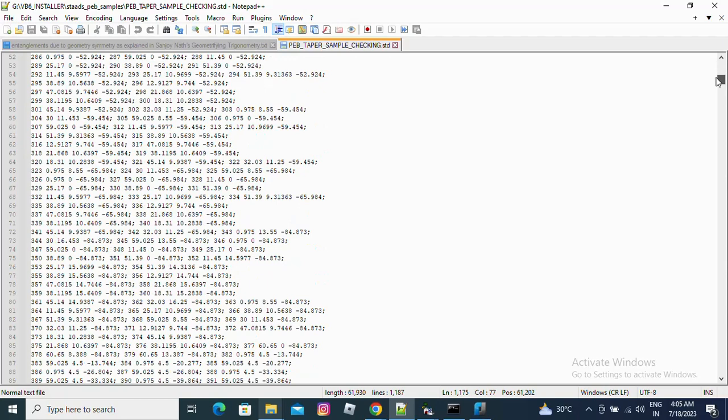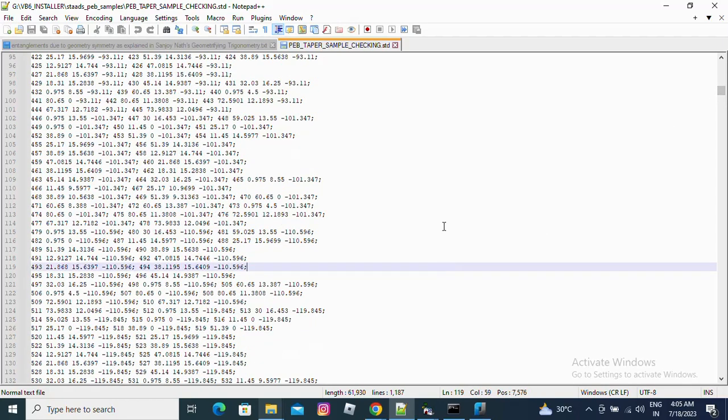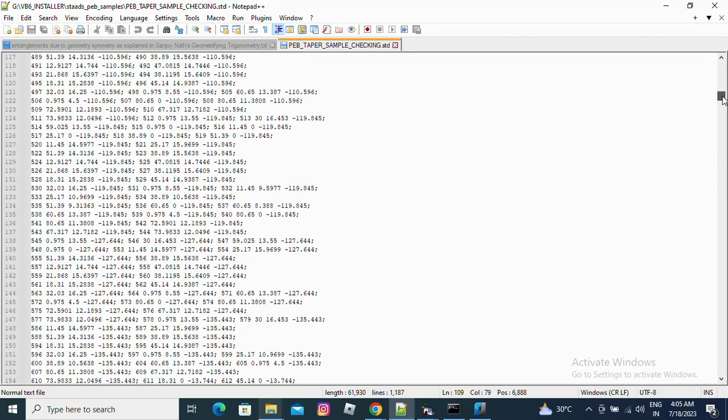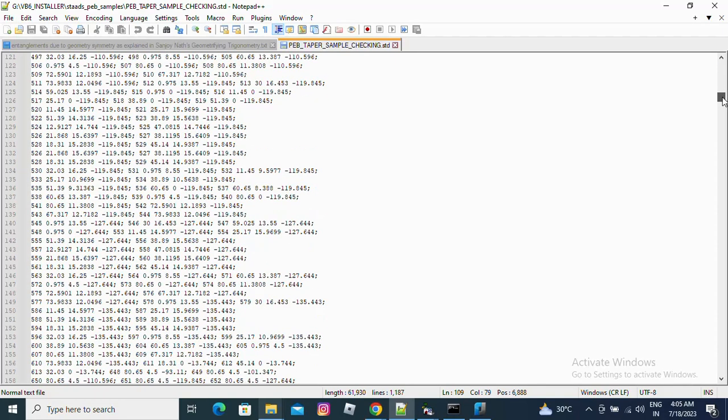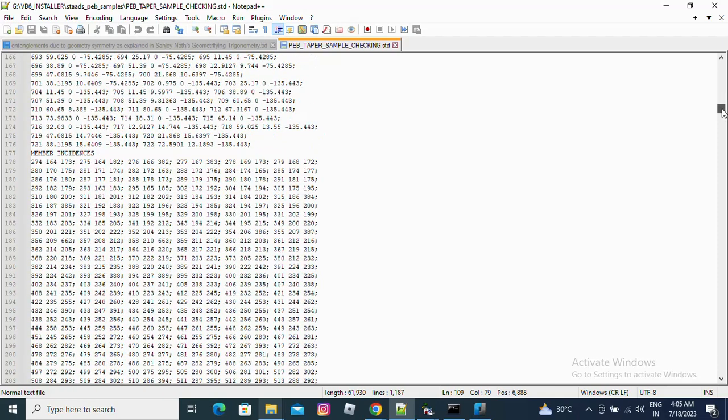We know that engineers have a big pain area. They need a lot of calculations to prepare these handover documents to scale and to prepare the material planning systems from the STAAD Pro files, because several kinds of profiles are used as tapered sections, and for tapered sections the flange reports are different, web reports are different. Webs are tapered with polygonal shapes, and those are trapeziums with multiple thicknesses.